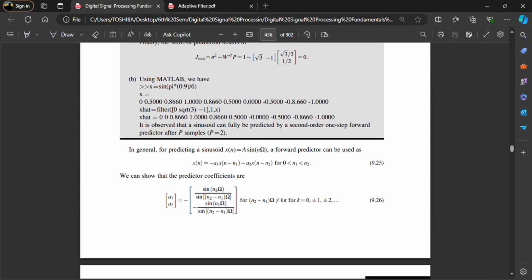Now moving towards the Wikipedia. The first example of this application is the recording of the heartbeat, which may be corrupted by noise from the AC mains. The exact frequency of the power and its harmonics may vary from moment to moment. One way to remove the noise is to filter the signal with a notch filter at the mains frequency and its harmonics, but this could excessively degrade the quality of the ECG, since the heartbeat could also likely have frequency components in the rejected range.